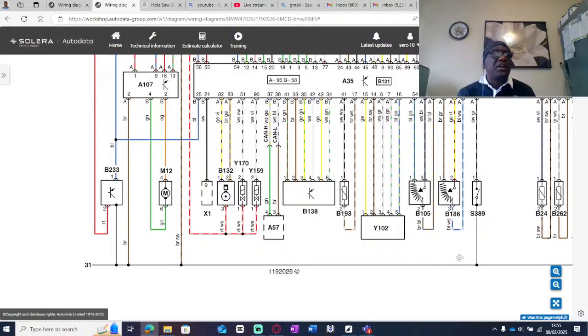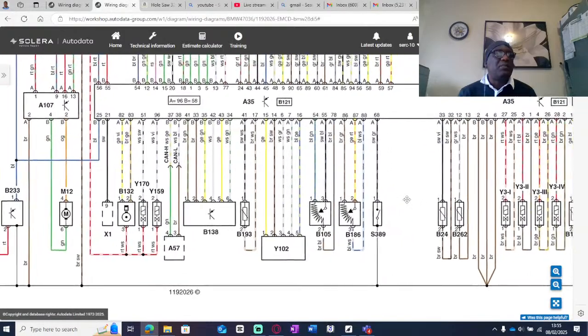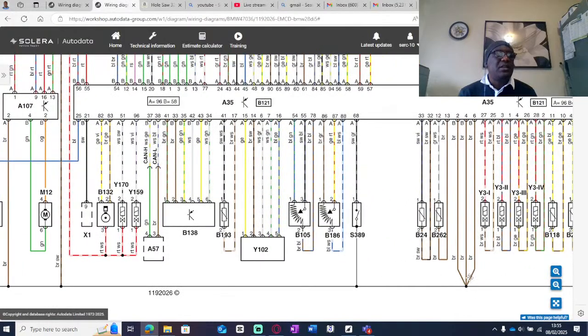So when you're doing your diagnosis, let's say you come here, you can see these 3 wires here. They all come from the ECU. So you have got 3 grounds for this ECU. Okay, and you need all of them. If one is broken, you can have trouble. So if you are diagnosing a problem, you check that all 3 of them are giving ground.